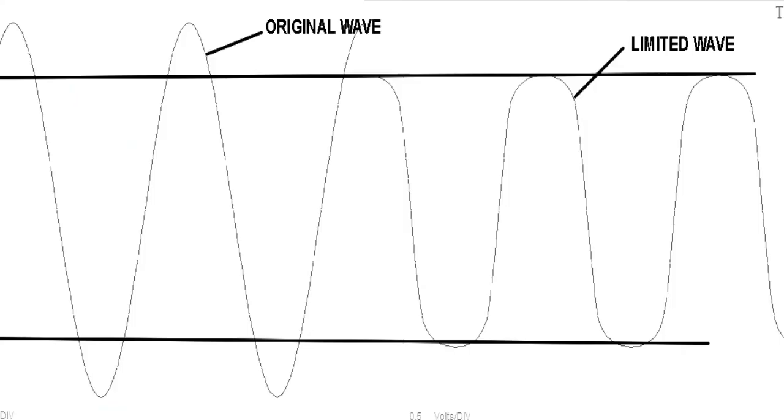Getting very slightly mathematical, the perceived volume level of this audio signal is the integral of the waveform, or to be clearer, it can be said to be the area under the curve. If the audio signal is momentarily reduced by a conventional limiter, the perceived volume dips. If the signal is clipped, there is no apparent dip.